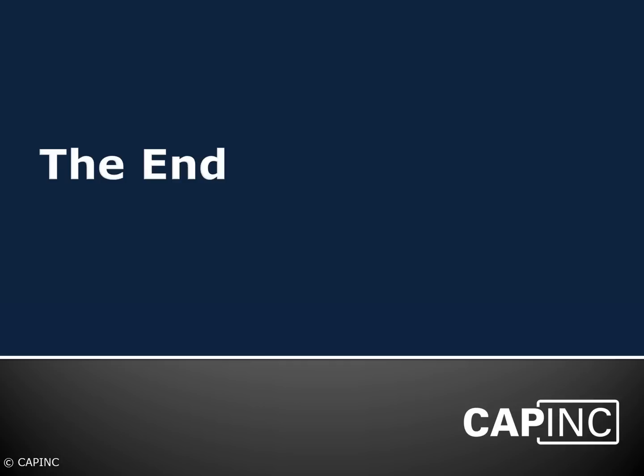Can you apply a template to a part or assembly after it's created? The answer is no. You would actually have to go and tweak those things individually. Unfortunately, there's no way of overriding its original template. It's just a starting point.